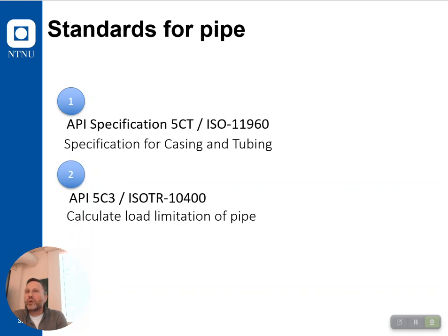Then you have to go to special calculations that consider wall loss. Theoretically, they do some of these, but that's not what we did. We said 12.5%. If there's more, scrap the pipe. And basically, it wasn't, because let's face it, 5% is the normal reduction.